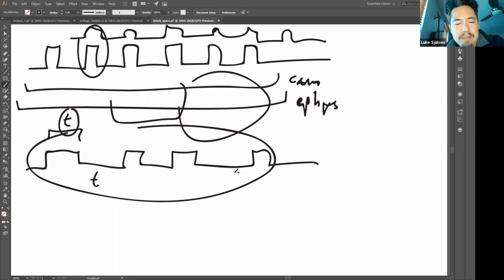Okay, so you're right. When you talk about the high enough frequency, if you're doing, say, a 30 hertz camera, then your pulses have to be at 15 hertz or less, right? So in this case you're vastly oversampling the pulse rate with the camera. So sampling and the Nyquist theorem and all that's not the issue. The issue here is that if you use regular pulses, then each second, or each say 10-second block of the experiment, is not uniquely labeled.